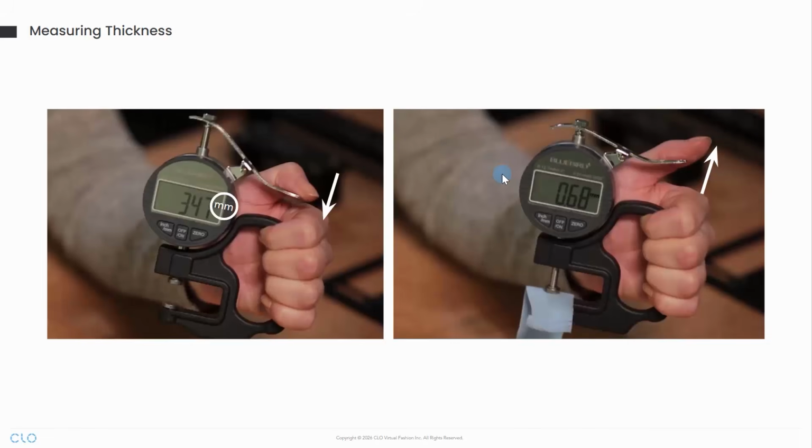Next, use a thickness gauge to measure the thickness. Turn on the thickness gauge and make sure it's set to millimeter. Then lift the lever, place the sample between the plates, and release it.